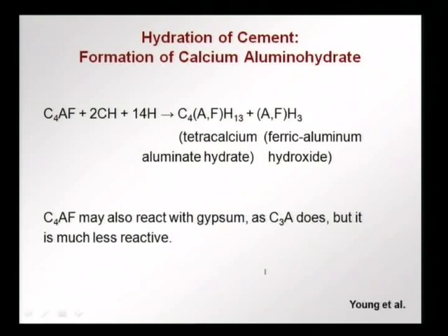C4AF also reacts with the calcium hydroxide to give tetracalcium aluminate hydrate and ferric aluminum hydroxide. C4AF can also react with gypsum as in the case of C3A, but it is much less reactive than C3A. So, these are the different reactions which occur when cement is mixed with water, and these are called the hydration reactions, and we have also seen what are the products that form as these reactions occur.